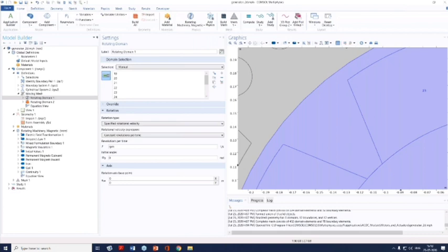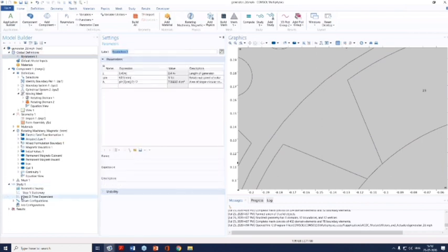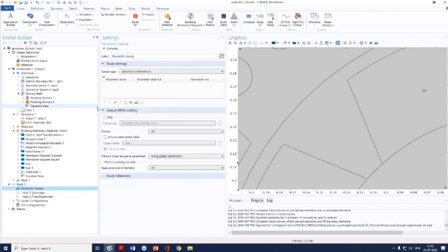How to do parametric sweep, parametric geometry with different parameters. Whenever you want to add any parametric sweep, you can directly have this parametric sweep. And let's say I'm having three parameters over here. Why they are right here in this case doesn't matter, but I'm just showing you how you can have a multi-parameter sweep. You can just add a parameter, provide the range. The next parameter also you can add, and the next one also you can add. So this is how you can add a multi-parameter sweep. This question will also be addressed in a better way when we are having a post-processing session on July 30th.